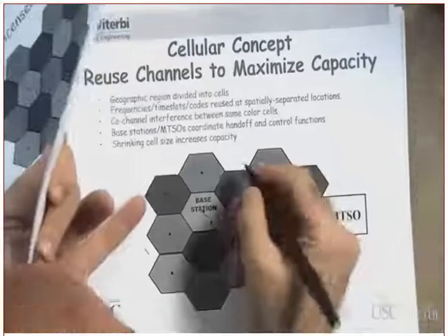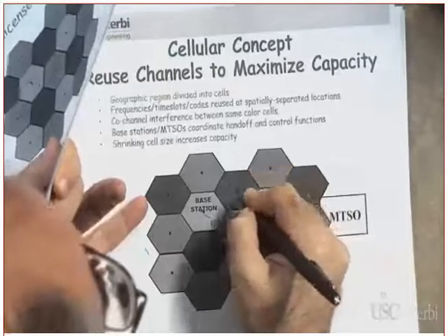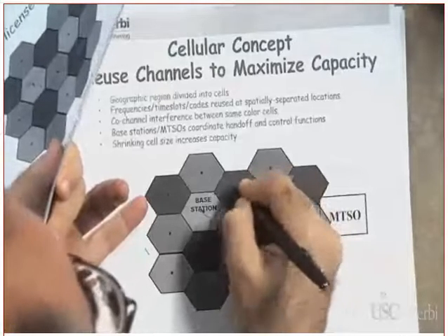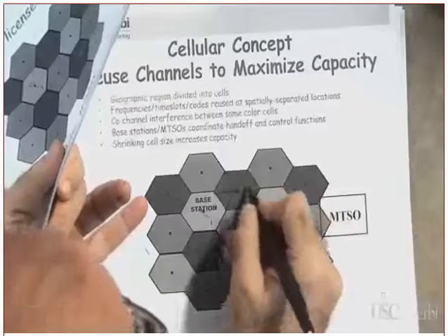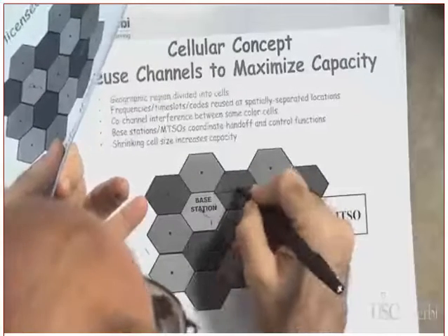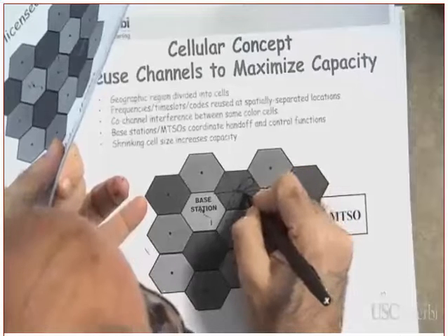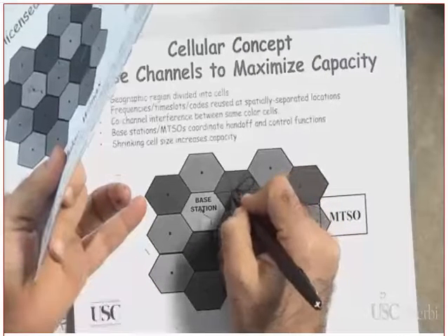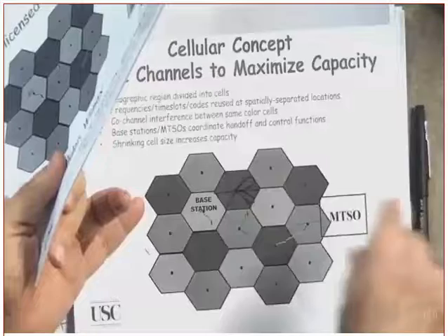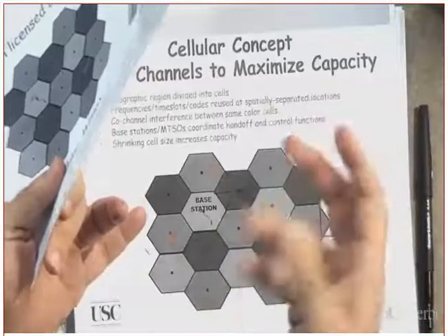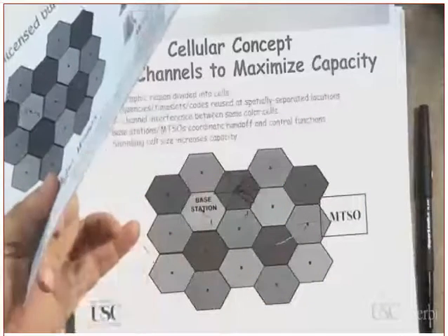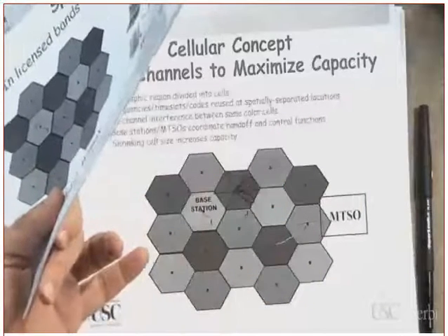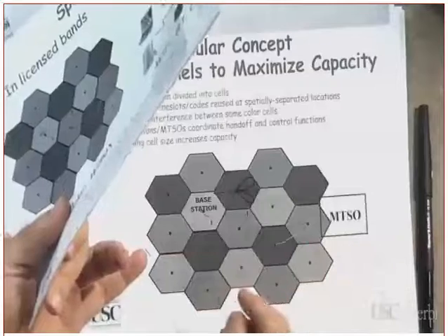The antennas become like this. This is the directional antenna here. I divide it into several sectors, for example 1, 2, 3, 4, 5, 6, and the antennas will become directional. Notice, by the way, the antenna will also have some side lobes and back lobes, but their effect will be negligible, especially the back lobes. Clear? You can reuse the frequencies to increase the capacity.